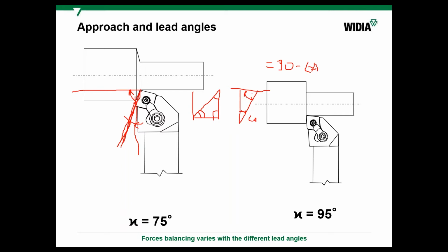In different catalogs, in metric and in inch, these values are sometimes shown. For example, in milling cutter catalogs, you can find milling cutters for 90 degree or 0 degree machining. Basically, it's the approach angle and the lead angle. In Europe, we use the 90 degrees abbreviation, and in the inch world, we use 0 degrees.